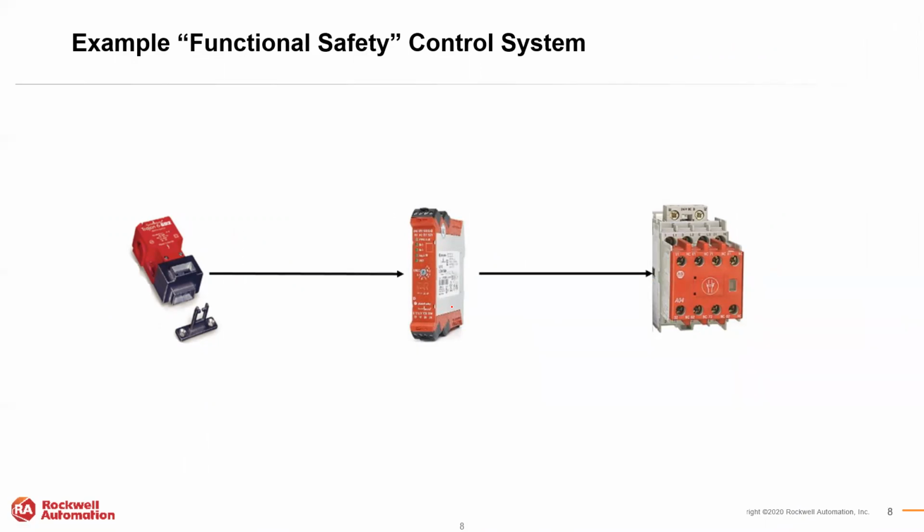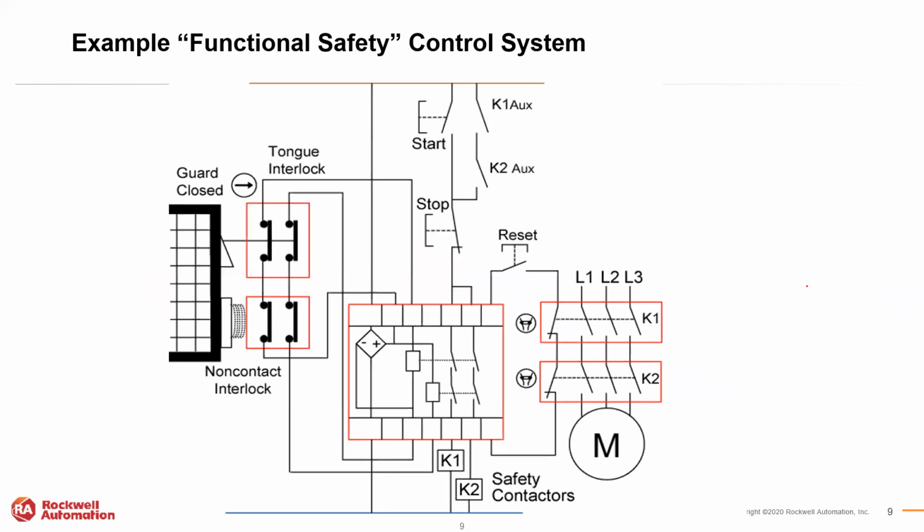From an electrical controls for safety and machinery interlocking standpoint, this is a very typical, very simple, not new technology for the most part. This is well established, where we use something like a guard door interlock switch of some type, this one being mechanical, some type of safety logic, and then some type of output, maybe a safety-rated device to turn a motor off, etc. Schematically, we might implement it something like this. This could be up to a 20-year-old design example. And we've got things like dual contacts. So if this wire falls off, our system knows about that and shuts us down to a safe state. Or if this circuit were to weld this contact, we would still have a backup and be able to get into a safe state.